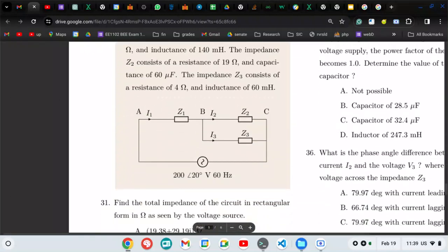Meanwhile, can you look at this circuit now? I don't know your name, the one who asked the question. Here, what happens? A part of the voltage is taken by Z1, and the remaining voltage is given to the combination of Z2 and Z3. Whatever that voltage is, let's call it V23, or VA and VB. Here the same logic applies, but because the same voltage is shared in series, there will be a problem. Sir, but if Z3 is connected, then Z2 would not be affected.